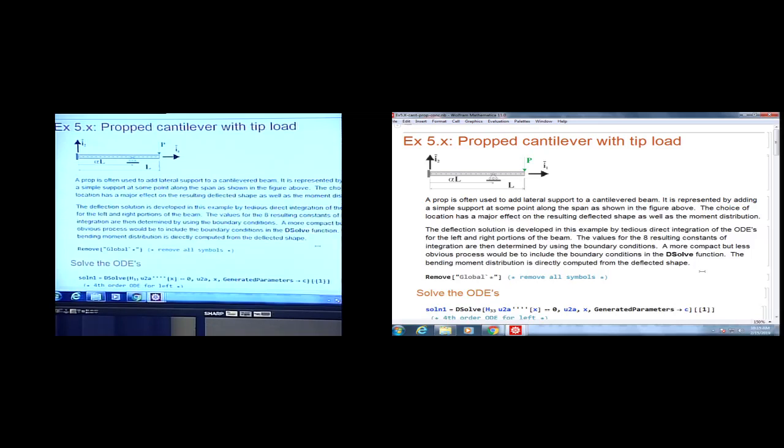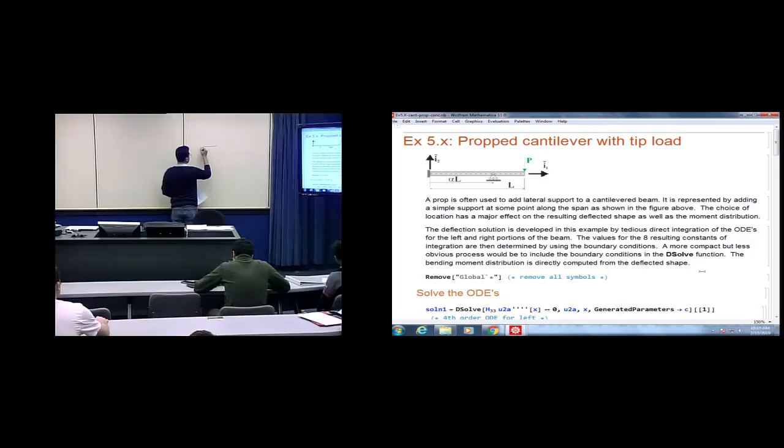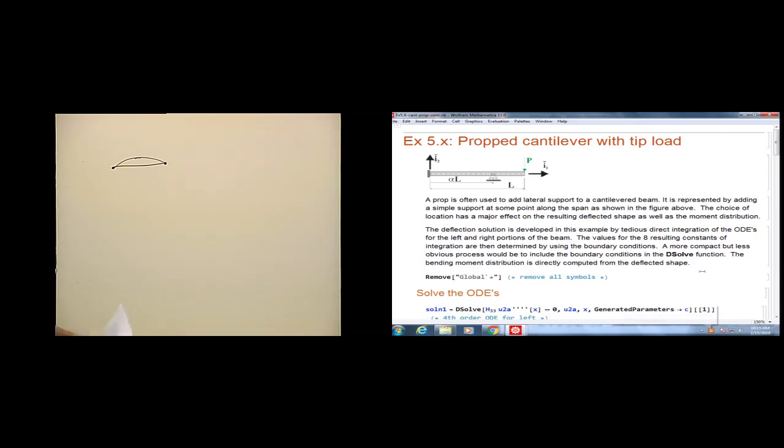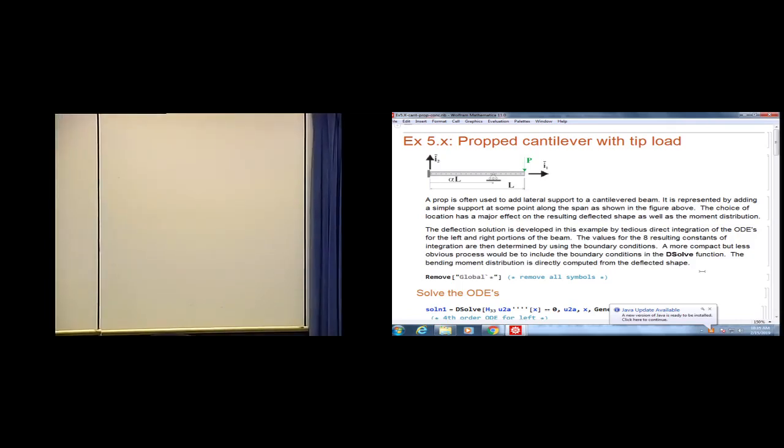Longitudinal displacement is allowed because it doesn't want any additional stresses for the beam in bending. For example, if I have a beam like this, and if I fix the displacement here and here, then if the beam bends, it would have additional stresses in the interior of the beam. The reason is that you are not allowing the actual displacement to compensate the length. So the displacement is allowed in the longitudinal direction, and it has no implications whatsoever for bending. The only thing it does is prevent the vertical displacement u2 at that point alpha L. So let's see what we can do for this problem.